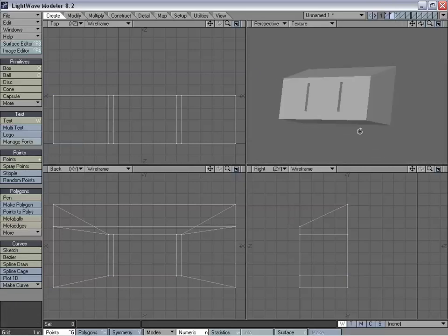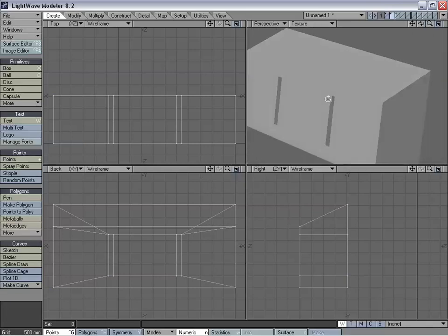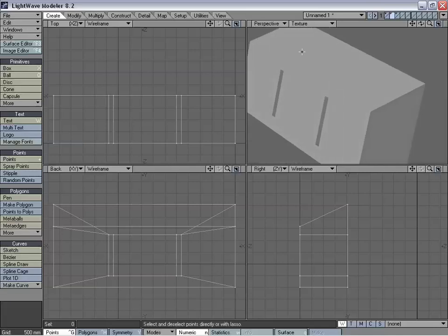Okay, and now we're going to create a beveled edge along the Merlon, so that it picks up some extra light. Because depending on which way the lights are facing, or the camera, as you can see right now, these two polygons blend into each other, and it looks like an odd shaped polygon, and it doesn't really have much depth because of that.